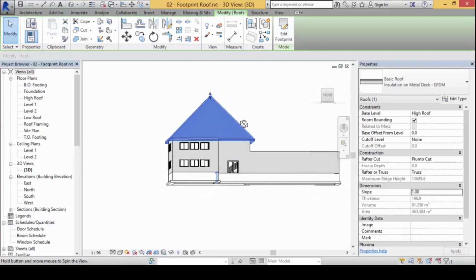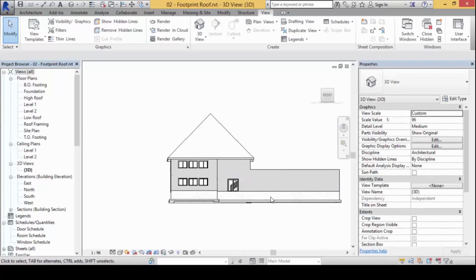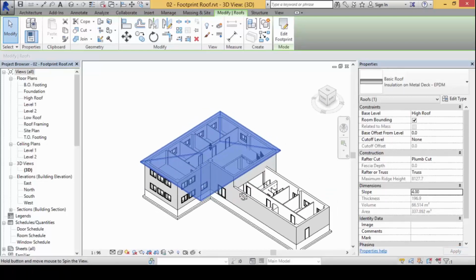You will notice right now, if I look at it in elevation, my roof is exactly 45 degrees pitch, because it is a 1:1 ratio. 1x equals 1y. If you have it at 45 degrees, you can actually create spaces in between, what we call the attic spaces. So we can lower this by increasing the number. The bigger the number, the more shallow it is. Remember 1:200 or not? So we'll put it, let's say, at 1:4, and then the numbers drop.